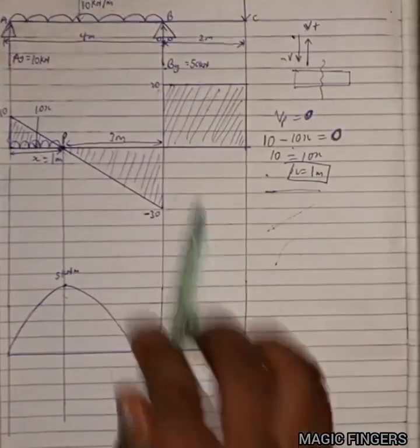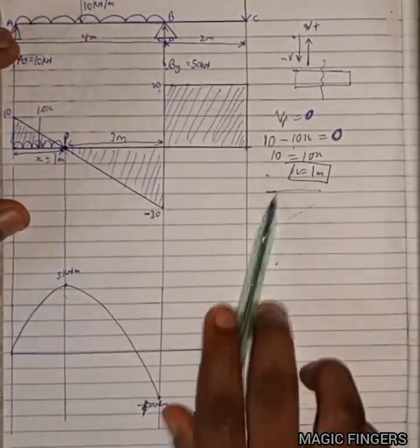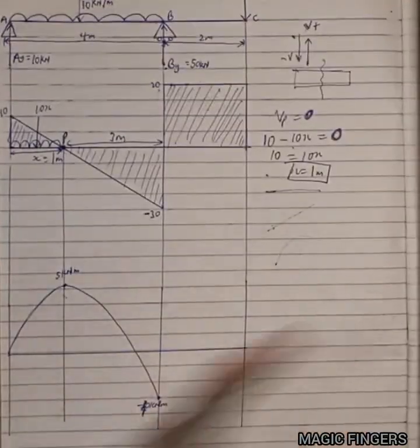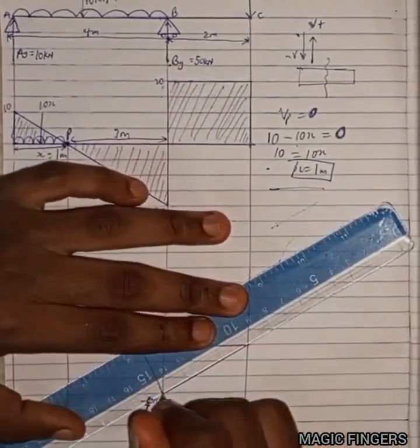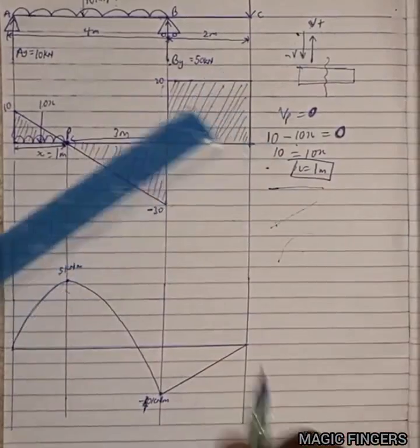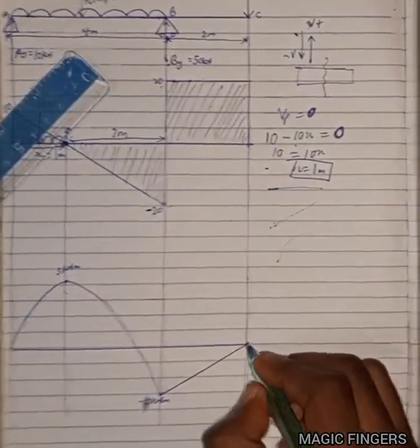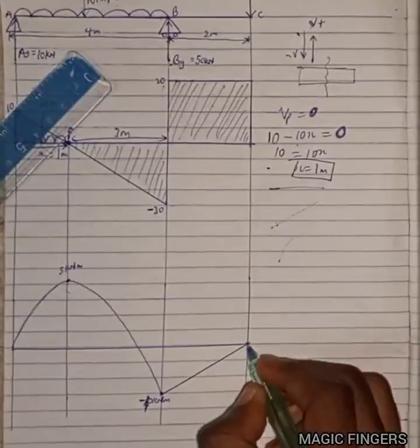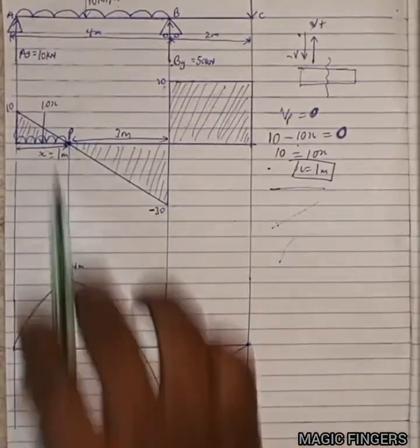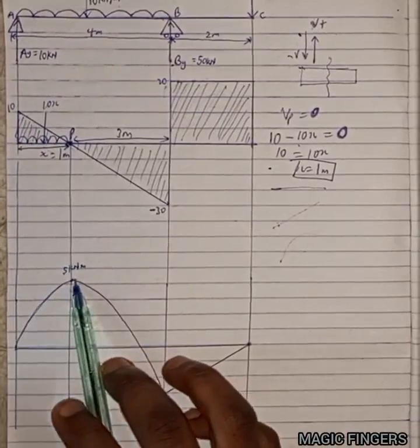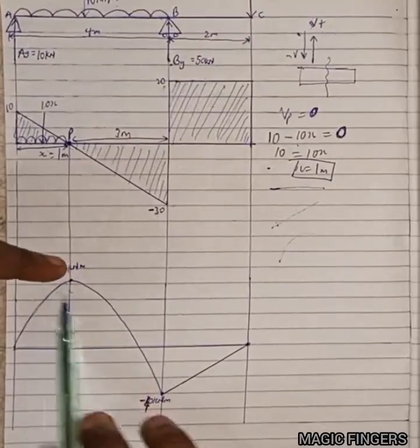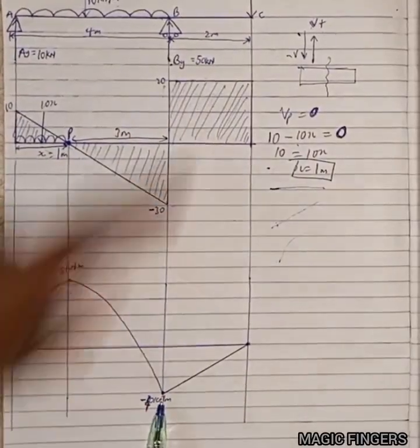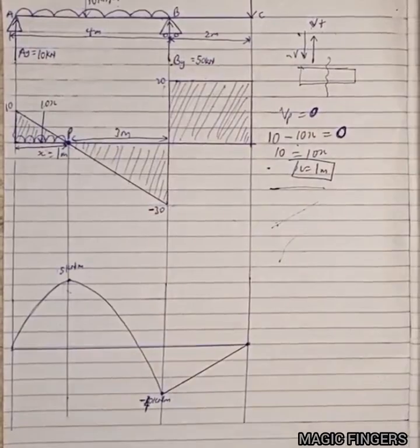So it is positive, and remember, this is a straight line. This one will be what? A line that will incline like this. Exactly. So remember, 40 is positive. So I have minus 40 plus 40. That will stop at 0. Again, the area of this one gives me 5. You draw a parabola. Next one, the area of this one is what? Minus 45. So 5 minus 45, I will have what? Minus 40. The area of this one is 40, like this. So that's that for that.